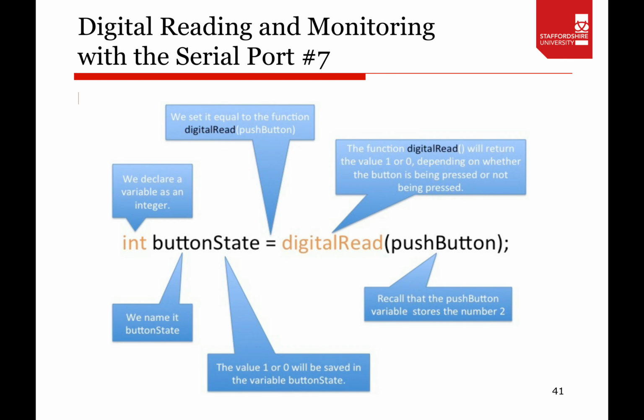So int button state equals digital read push button: we simply declare a variable as an integer. So the returning value from this function is an int. It's being named button state, so the state of a button.